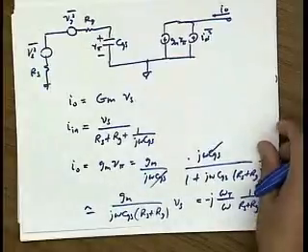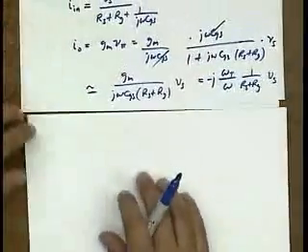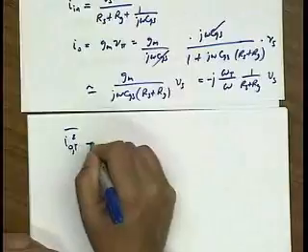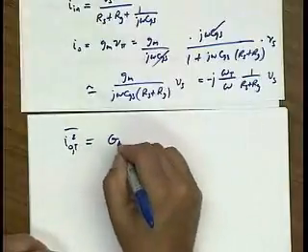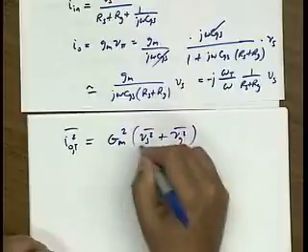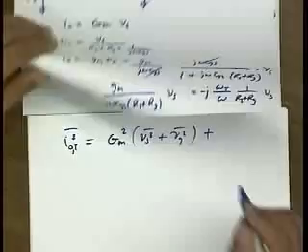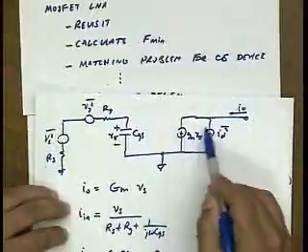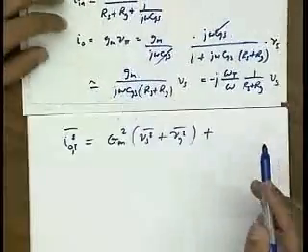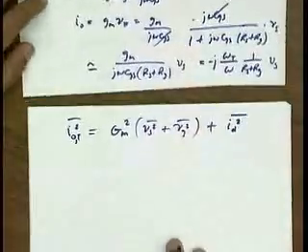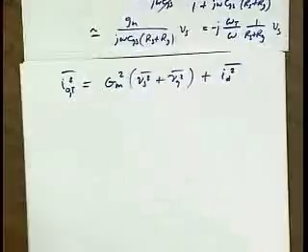And in fact, you can see that it allows us to very quickly calculate the output noise, the total output noise. Total output noise, therefore, is just Gm squared (Vs plus Vgate) plus, if I go back and look here, total output noise is this drain noise plus the current gain, which we've already included. And so this is the drain noise squared. Okay. Any questions?